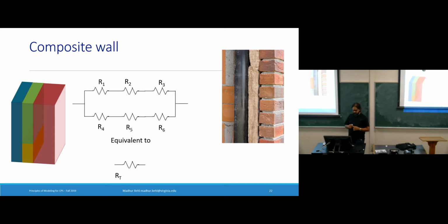And so then the question is, how do we model the thermal resistance of this wall? Well, you can now use any property of resistance, right? What we've learned is, we know that resistances add directly in series and in reciprocal when they are in parallel. So in this thought experiment, the middle layer is green and orange, right? So it's a composite of two layers, and then there's a blue layer and a red layer.